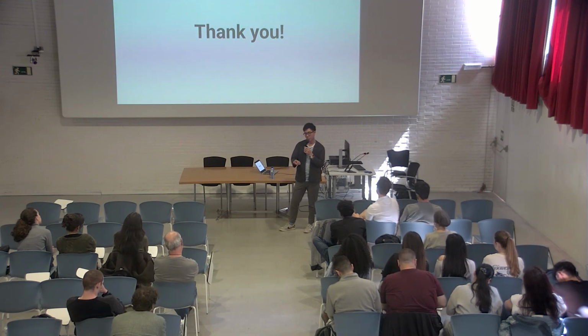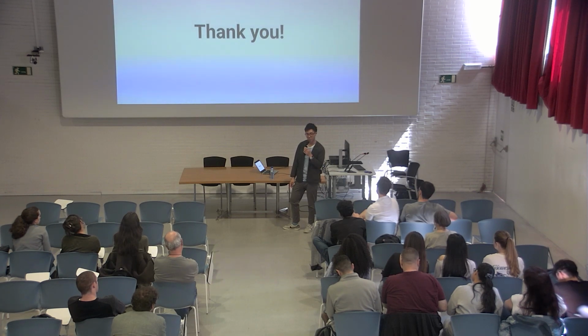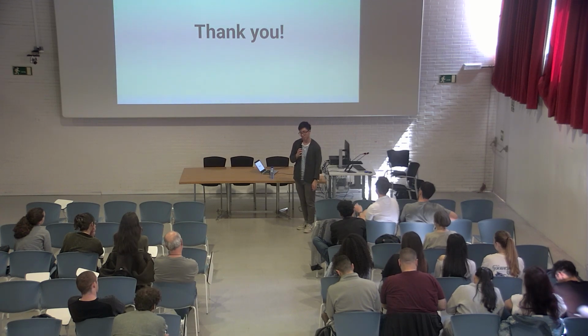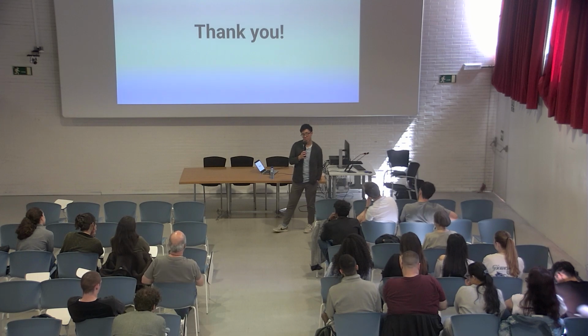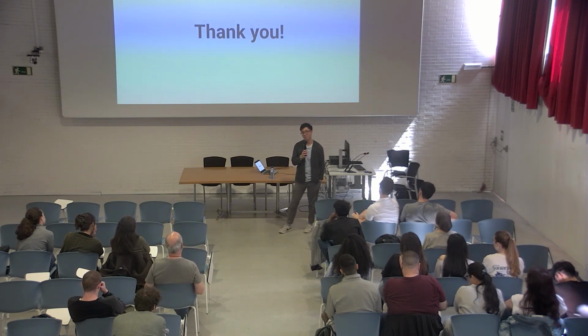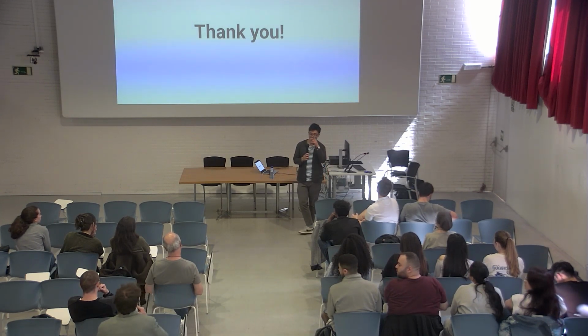And if it's not performing as you intended, understanding why it might be wrong. This often might be a definition in terms of how you set up the connections, for example, or buckling length, which is a very common issue that can make your structures perform much better than they actually do in real life. So there are many great advantages of using Karamba in teaching, and we can see that already with a lot of the students and teachers who use it in academia. But as I mentioned, there's always this drawback that there is a misunderstanding of what Karamba can do too. Okay, thank you very much.